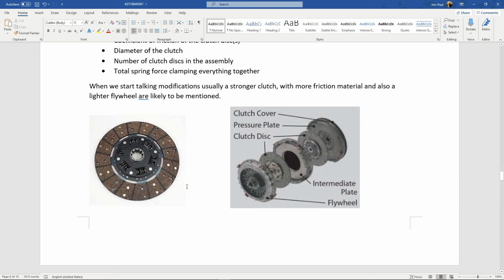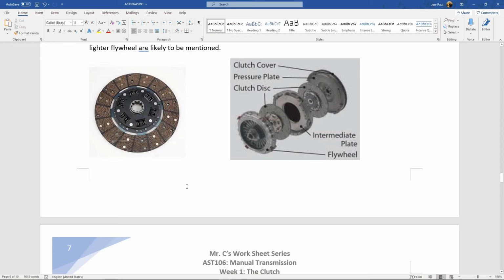So a clutch will affect the entire transmission equally, whereas the much more likely, if you have grinding, this is what they always tell me, it's like usually second gear or first gear. It's either from launching hard on drag racing or people downshift into second hard, and that'll cause the synchronizers to fail for that gear set.